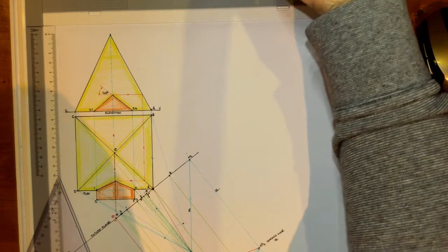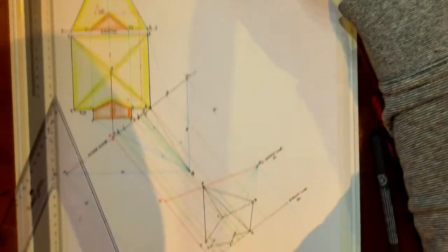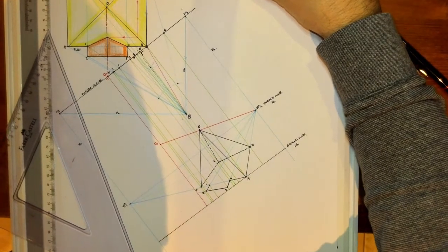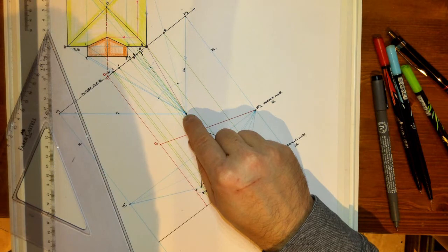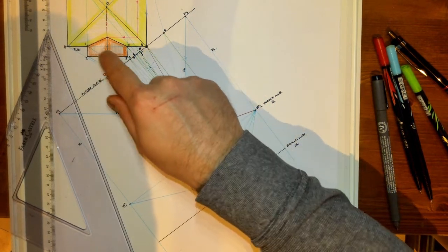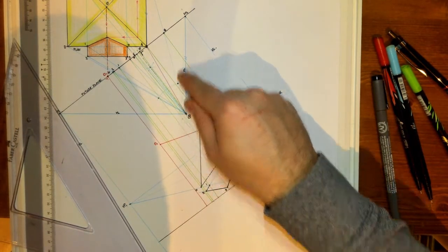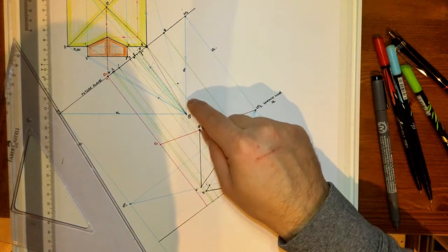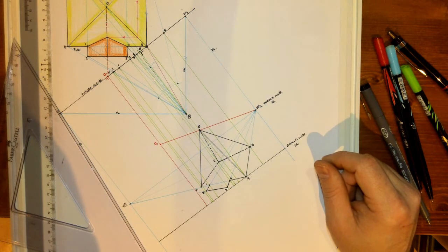Okay? And what's important here is that I'm noting the angle here in the elevation, which is 40 degrees. Alright, and what I'm going to do is go to the plan view, and go to point S, and depending on whether the surface you're trying to find is facing the vanishing line here or the vanishing line here, we use either one of those lines as our guideline for finding our vanishing point, our extra vanishing point.